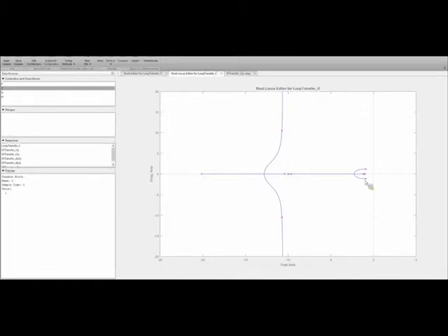So if we look here, we have a pole zero cancellation from a closed loop pole and an open loop/closed loop zero, same thing. And we have one here as well. These are really close to each other. So we're saying the system mostly responds like these complex conjugate poles here. And this has, as rough numbers, a natural frequency somewhere around 10. It's a little bit larger, but the rule of thumb is to make the zero of your lead or your lag controller an order of magnitude smaller than that. Okay. So if I were to look at this in the frequency domain as well.